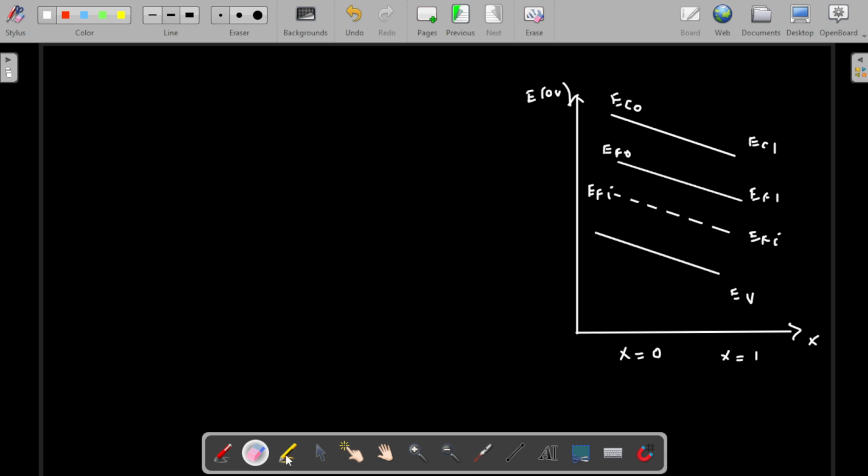One more piece of information they have given is the band gap, so we have that information also. Then we have been given the applied electric potential. So the potential can be found: 1 volt is applied across 1. So dEC by dx, the slope of variation, will be minus 1 eV per centimeter, because that is exactly opposite, right?